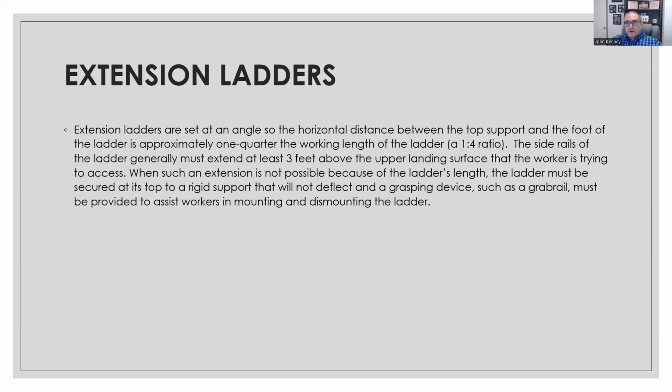To clarify that, your ladder must always extend properly, and you need guardrails where they must be. If a ladder does not extend three feet or above, then you need to find another method or get a longer ladder, whatever it may be. But being a foot above the roof does not meet the standard.